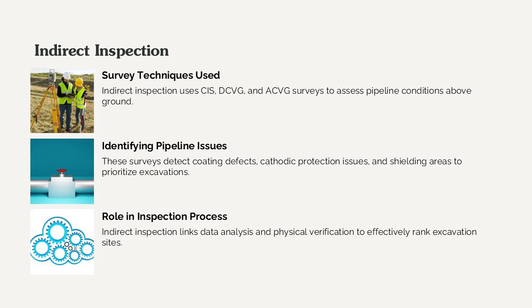While indirect inspection methods do not detect SCC directly, they provide valuable indicators that help rank excavation sites. The effectiveness of this step depends on proper survey execution, data interpretation, and integration with pre-assessment findings. Indirect inspection serves as a critical link between data analysis and physical verification.